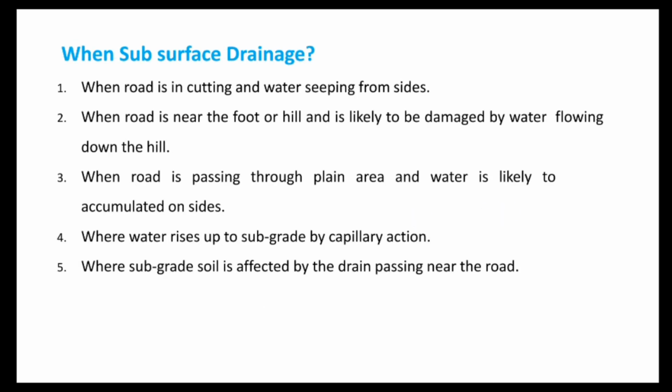So where should we provide the subsurface drainage? Subsurface drainage becomes essential when the road is in cutting and the water is seeping from the sides.